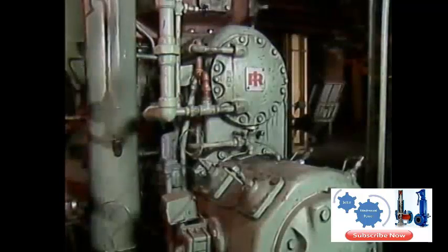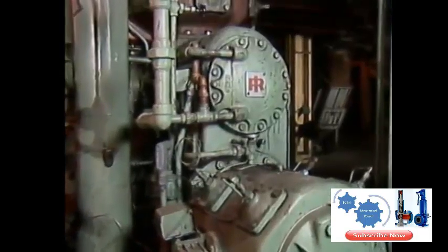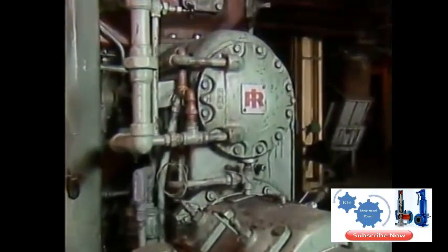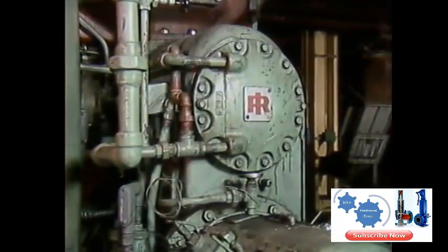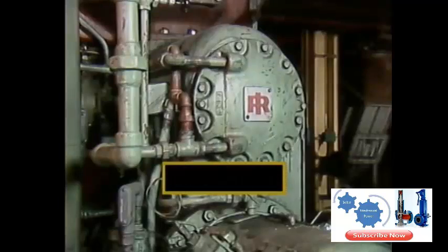The other method of water cooling cools just the compressed gas. This method involves one or more shell and tube heat exchangers. Depending on their location, these heat exchangers are classified as either intercoolers or aftercoolers.